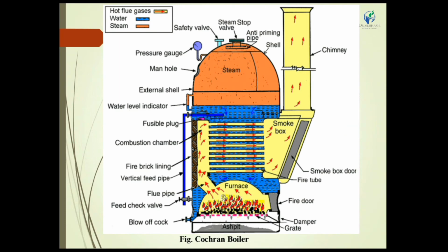The steam formed from the water is collected in a steam drum or hemispherical drum. Then a pressure rise is created, as the volume is constant. The collected steam is passed out from the steam stop valve for further utilization. In case heavy critical pressure is created in the boiler, the safety valve operates and gives the steam out from the boiler.